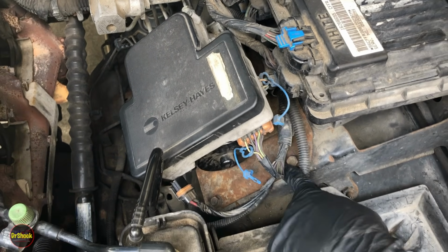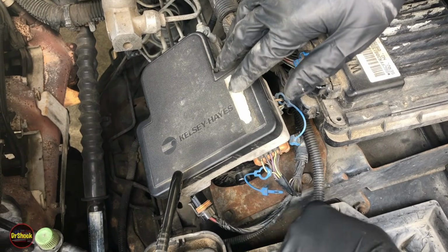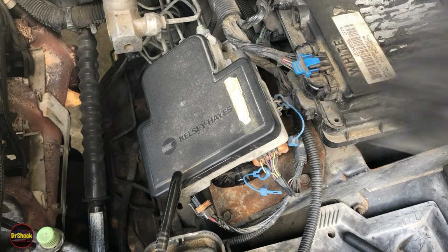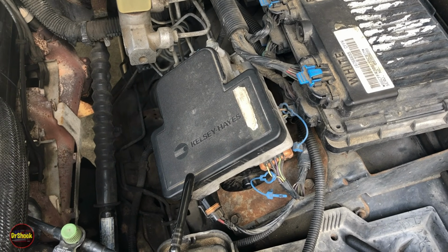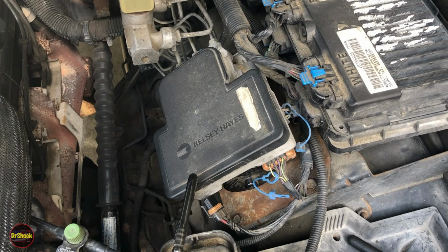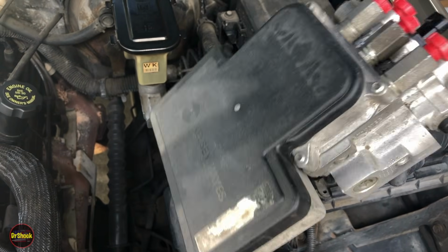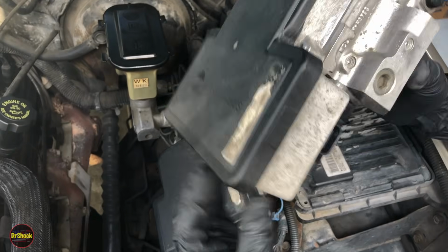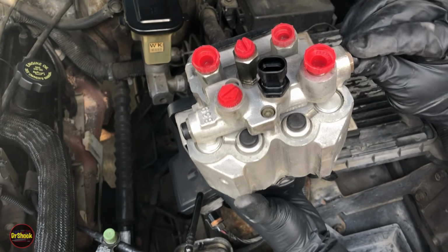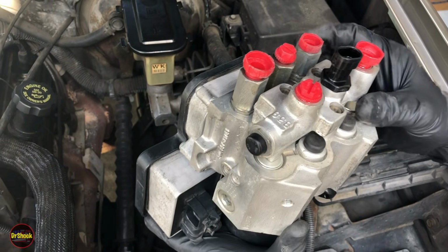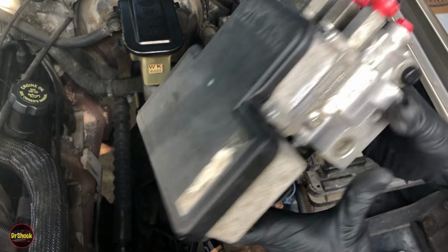I'm going to go ahead and take these two 13s off on this side. There are two more on the other side. We're going to lift this guy out, mounted to this mounting bracket, intact. Let me show you the one I'm going to be putting in here so you can get an idea of what we're dealing with. This is a salvage yard EHBU that I've refurbished, right? Cleaned it up, polished it up, checked and made sure that the pump passes its tests, got it in good shape. We've pulled off the bleeder covers and cleaned everything off there. We've tested and made sure the switch is okay. Of course, we've got these guys on here so that we don't have any brake fluid dripping around.